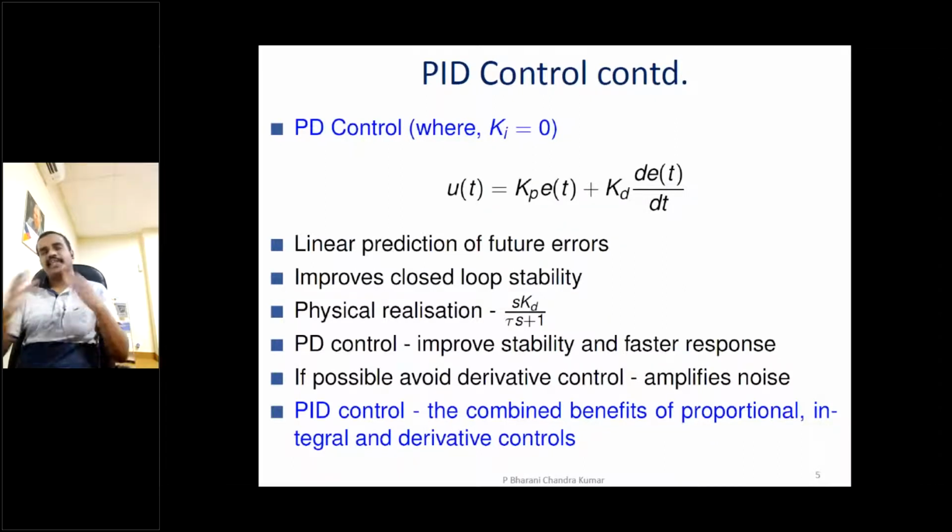Listen very carefully to how the Ziegler-Nichols tuning works. Only the proportional gain is connected to the plant in cascade, and every loop is removed, and you keep on changing the gain value until you get the oscillatory response. So only the proportional gain KP, the feedback loop has been broken, deactivated.